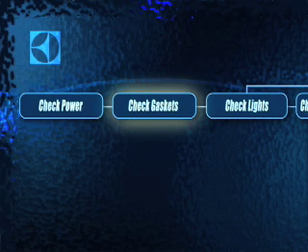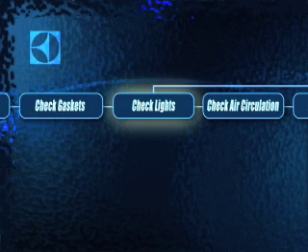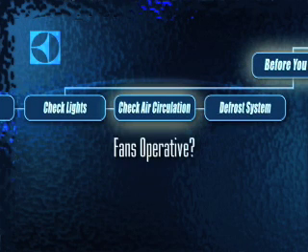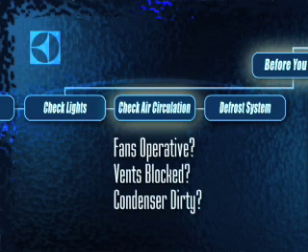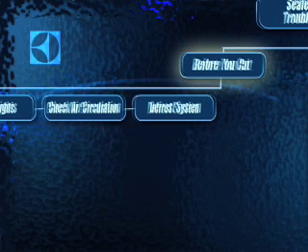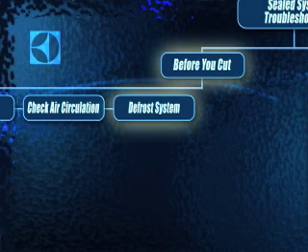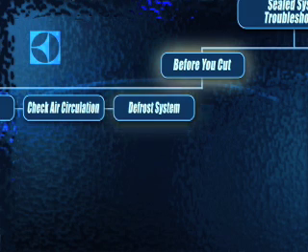Check the gaskets for leaks or imperfections. Are the interior lights staying on, causing excessive heat? Check all the fans. Also make sure interior vents aren't blocked and that the condenser isn't excessively dirty. Finally, is the defrost system functioning properly?